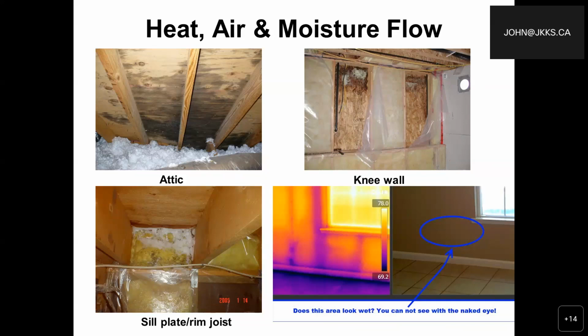Over time, we can see that it's starting to darken even the plywood sheathing on the floor system. Over time, if it remains moist, we're going to have rotted wood floor joists, or potentially even a rotted wood sill. Again, not uncommon things that do occur, but again, an explanation of why we take a look at building science. Why do these things happen?